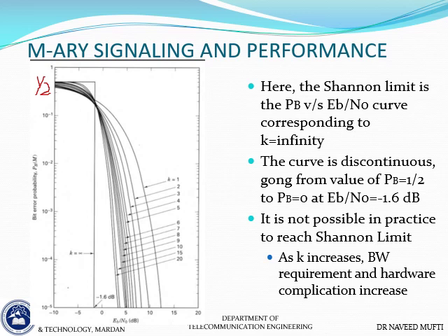So we will always be somewhere here. So that's what we need to remember, that there is a limit on Eb/N0 which we cannot even attain practically. And even if theoretically we were able to attain it, beyond that, we don't have error-free communication for any information rate whatsoever.